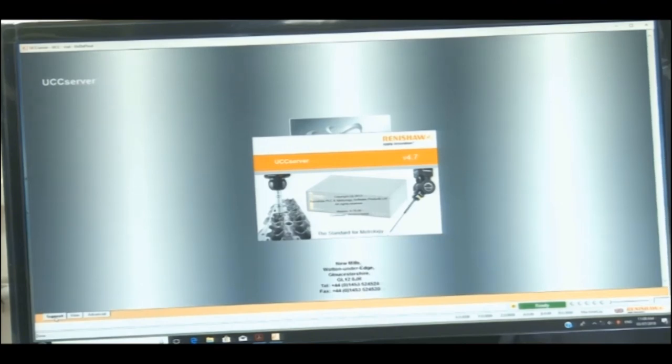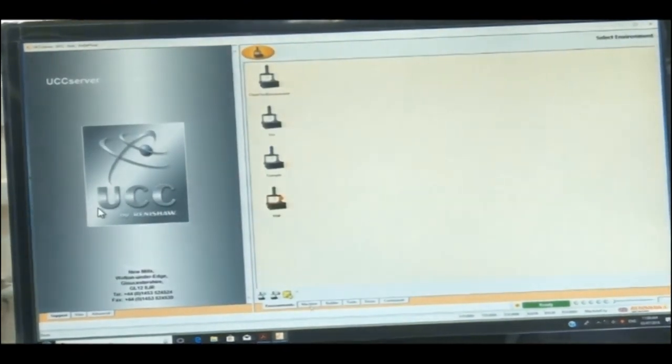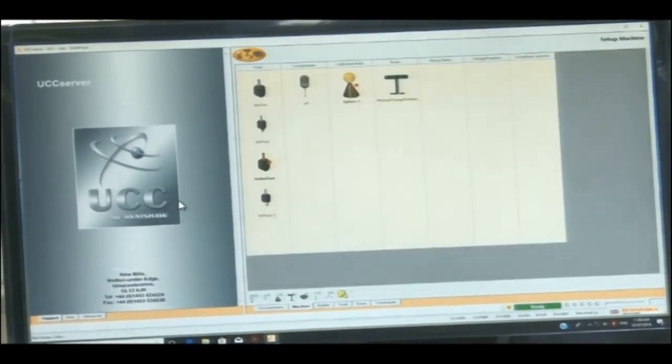All these things are components of the coordinate measuring machine. The purpose of the UCC is to permit control of the CMM from the front end software. The controller provides the control signals to the CMM probe system necessary to give the required response, for example, to position the target to the given parameters.